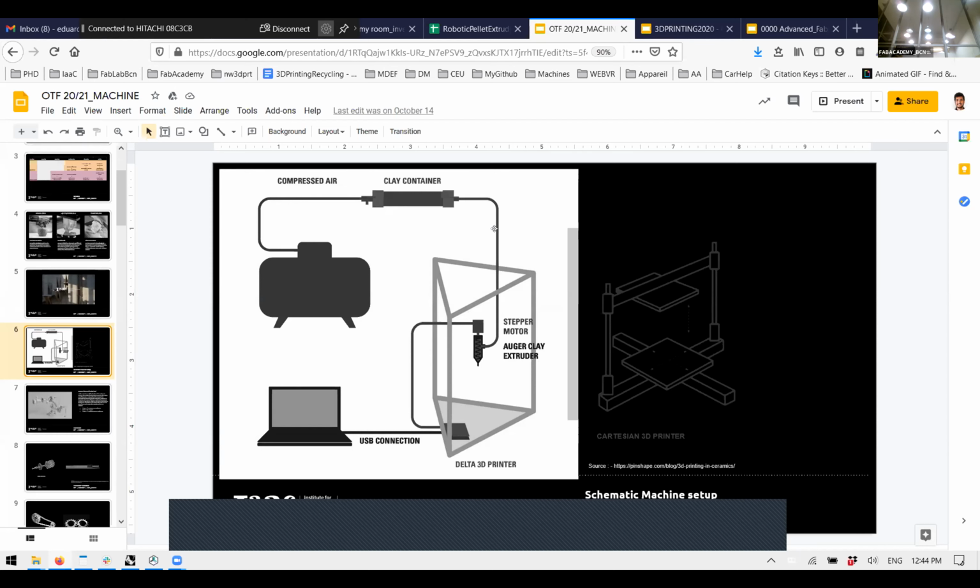So the cartridge is all the time at full pressure to feed the screw, and what actually controls extrusion is the rotation of the screw. This screw is called a degassing screw, because by compressing the material on the thread of the screw, the air bubbles go up and the material goes down because of the screw geometry. And this actually makes all the difference. It makes a huge difference having this.